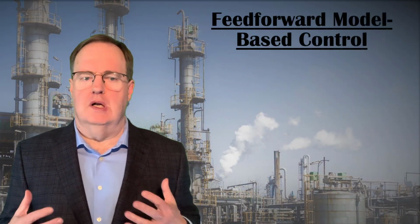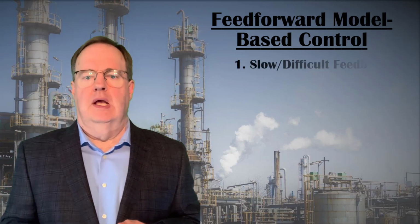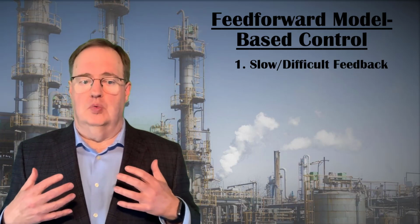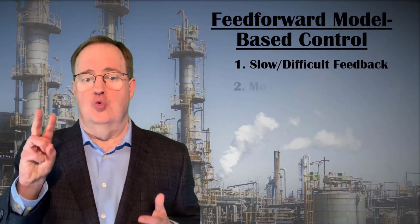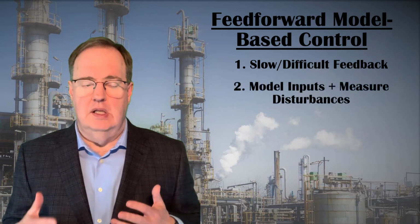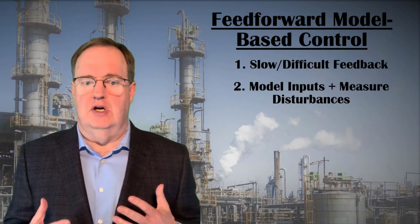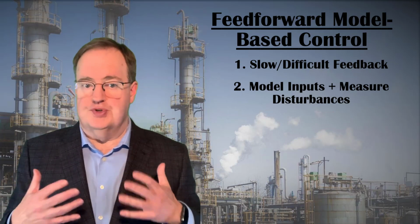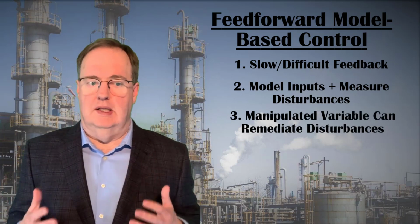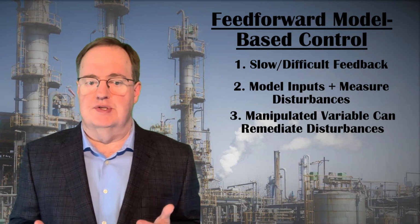Opportunities for feed-forward model-based control require the following process characteristics. 1. There is a dynamically slow or difficult to measure process variable which is key to some objective. 2. We can assemble a model, either steady state or dynamic, to predict that variable with model inputs from other measured variables, especially variable sources of disturbances. 3. One of the model inputs is a flow that we can manipulate to remediate the disturbances.